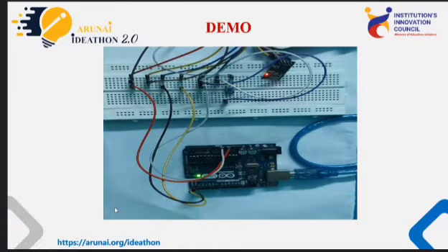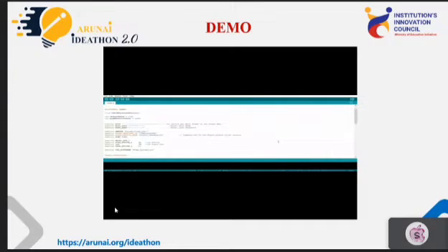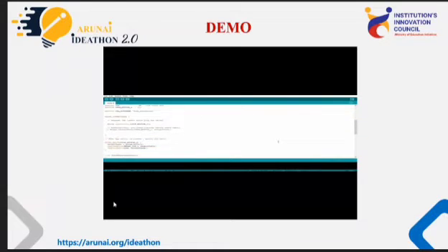Using jumper wires, we are connecting Arduino UNO to ESP01 to load the program. And this is the Arduino IDE page. This page will include all the libraries which we need, and then we install the Blynk app library. By using this program, we connect data to ESP01 with the help of Wi-Fi and password, and also set up the Blynk app on a mobile phone because we can control it anytime and anywhere. In the Blynk app, we can control our software.